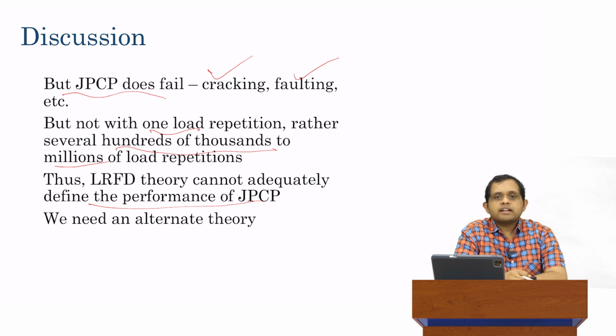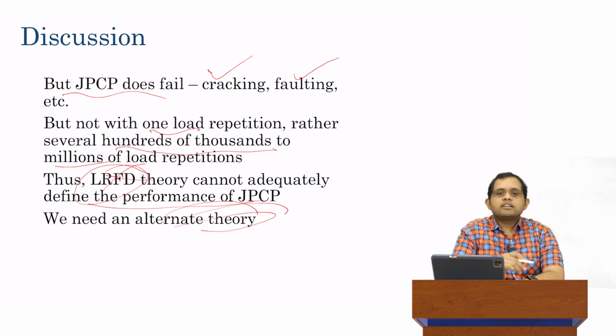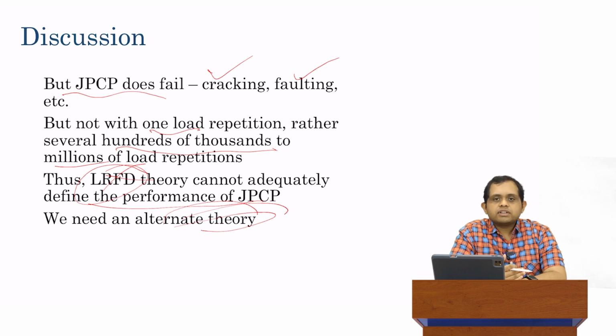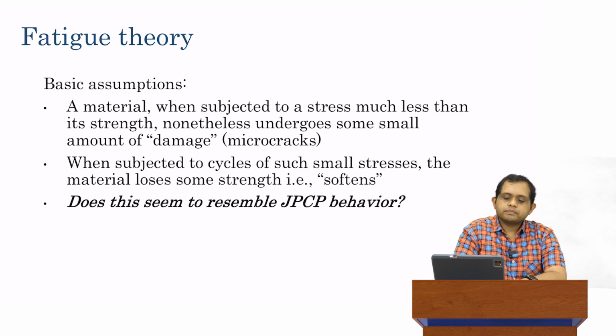It is for these reasons that LRFD, while so successful in structural engineering, is not and cannot be used in pavement engineering. It would be nice if we could use LRFD because as civil engineers, we have a lot of experience using it. But since we established that we cannot, we need some alternate theory, something else that can explain the fact that the pavement does not develop distresses immediately with one load application, but the distresses develop progressively due to very small stresses, much less than strength, over repeated loads.